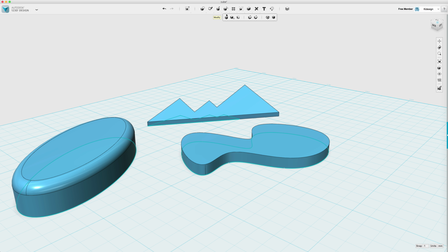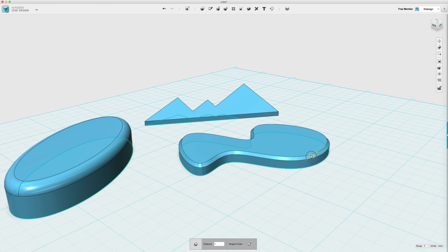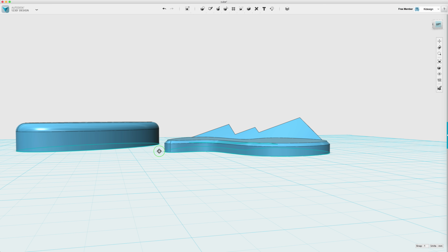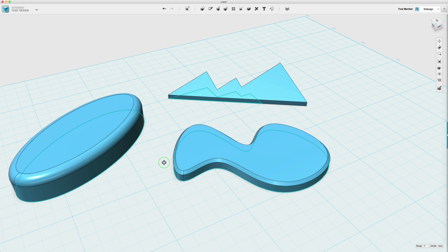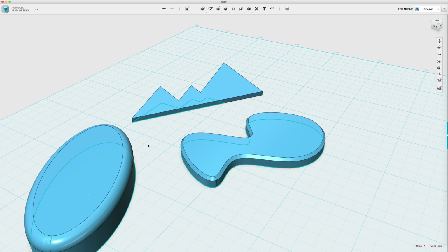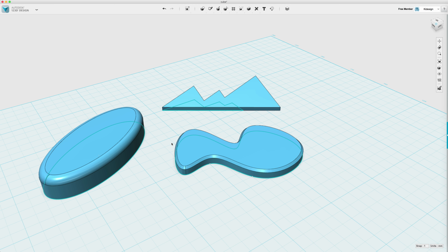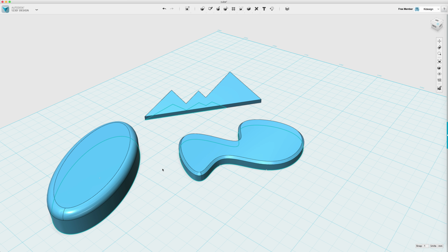And to show you how to do the same thing with the chamfer, we'll do it on this one. Select the edge, and now I can drag it and say, I want to, now maybe a bit less. So you can see this same function, well, I mean same purpose, but it's just rounding the edge here, and here it's slicing it. Another useful tool is shell.